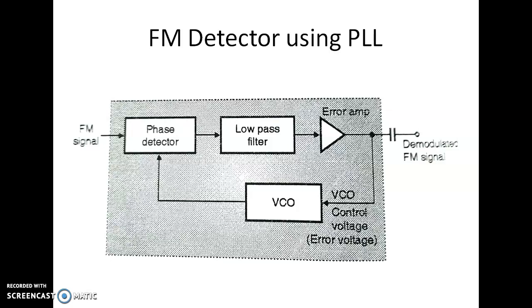If you consider the frequency synthesizer, then in that case the circuit will be the same as that of the frequency multiplier, except for a divide by M network, which is added on the input side after the crystal oscillator. We have to add that after the crystal oscillator. So the frequency synthesizer is supposed to produce an output signal, the frequency of which can be precisely adjusted to any value in a selected range.